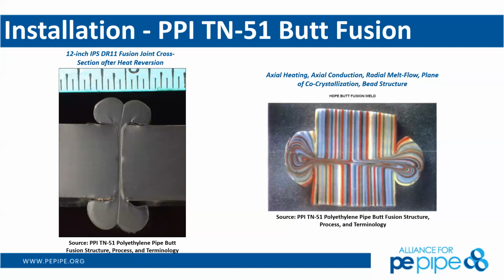You can see with the colored one there, that's not just a candy colored pipe. We did that to show how those melt flows go. So you'll see how the interface of the two pipes coming together under a high temperature has allowed those links to open up. Then putting it under pressure, you have that joining, and then you see the excess pushing out to the edges. Again, that excess doesn't have anything to do with the pressure rating. It's fine whether the exterior or the interior is removed.